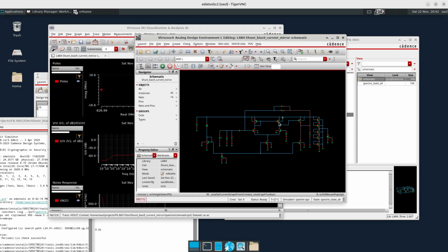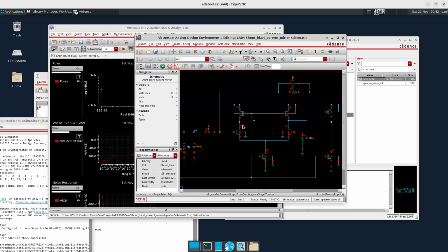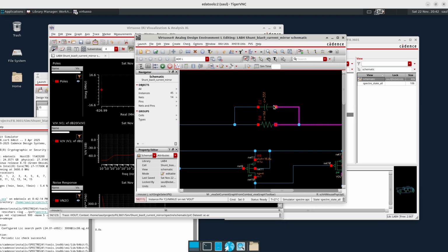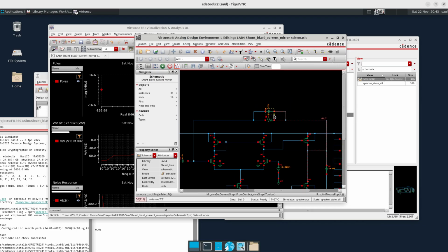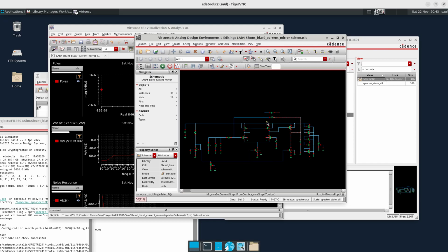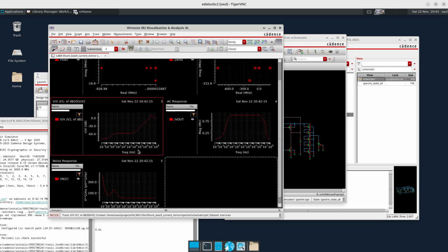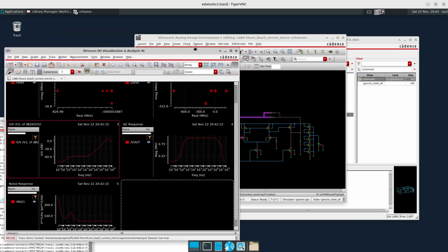The reason is that we have another pole here that is basically contributing to the number of poles in the system, and the compensation needed to be changed a little bit also to avoid some peaking there. On the other hand, even though the high frequency value has changed a little bit, the noise performance we expect to be a little bit better.